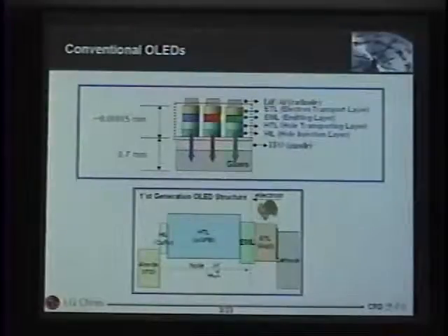Copper PC was the hole injection layer, which stabilizes the interface between ITO and the organic layers. They used a hole transporting layer of the arylamine type and an emitting layer, in previous times, like ALQ3, and also used ALQ3 as the ETL. The mobility of electrons was quite slow compared to the mobility of holes. Nowadays people are trying to fix those problems, and they like to reduce the hole mobility and also increase the electron mobilities.